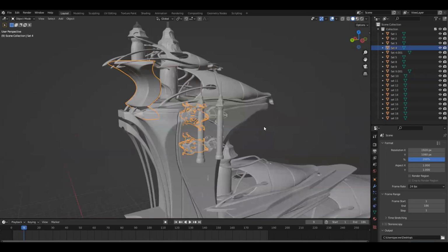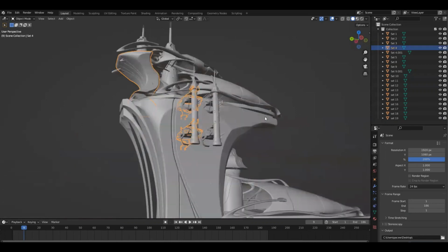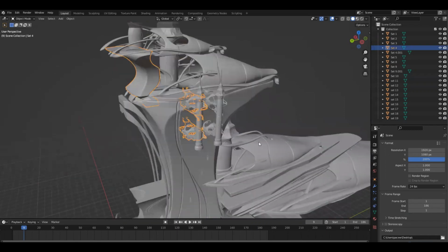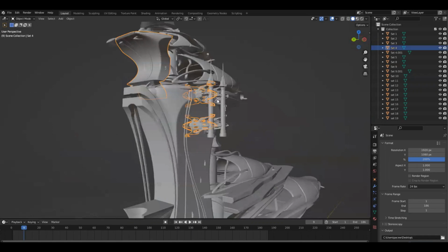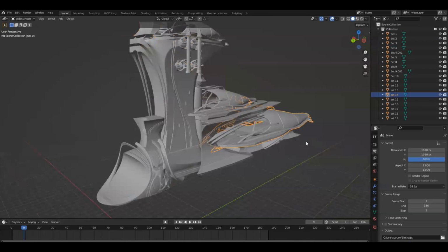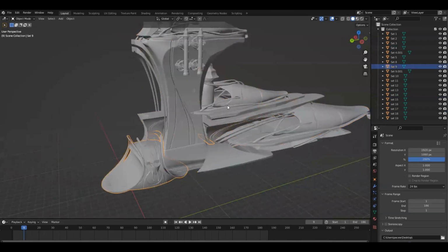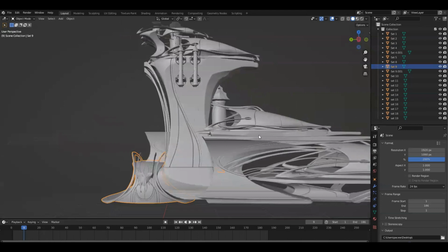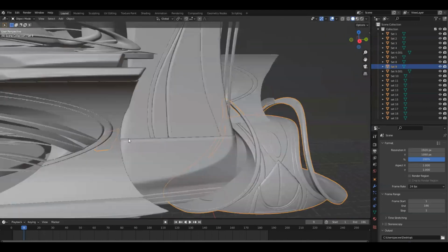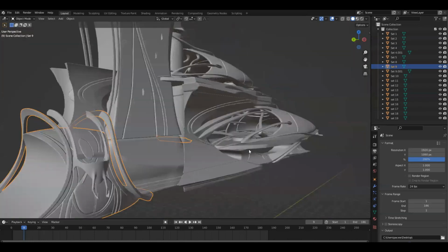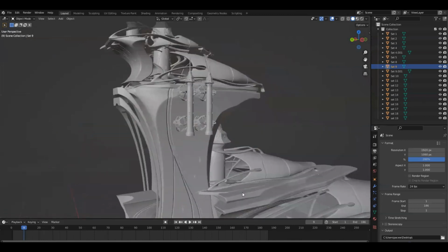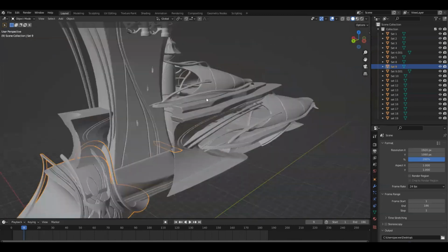And remember, because we exported them in sort of random segments from the 3D Coat layers, they're separated and grouped up in ways that don't really make sense. So these objects probably shouldn't be in the same object as that, even though that's just what happened from 3D Coat. In this doorway object, you'll see there's a piece here, which I think must have been a Voxhide segment, because it's not actually even visible. So we're going to want to delete that in a second. But yeah, there's a little bit of cleanup to do here. So let's do that real quick.